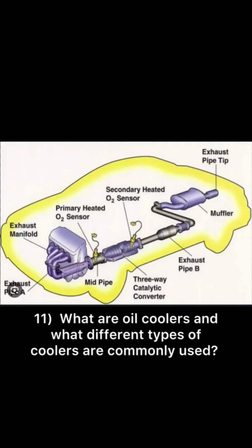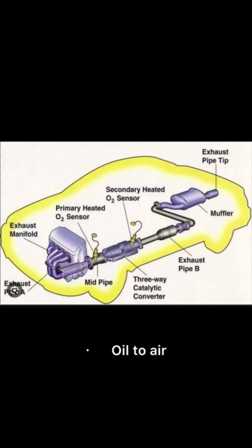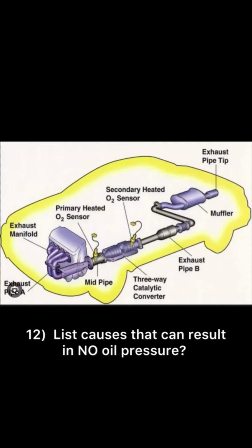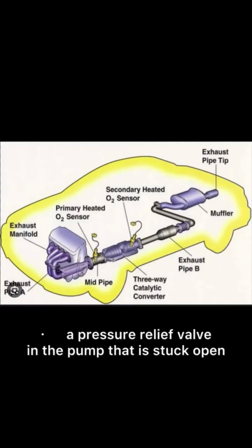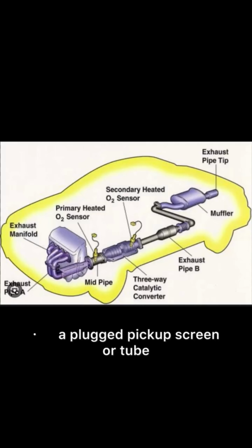11. What are oil coolers and what different types of coolers are commonly used? Oil coolers are heat exchangers that transfer heat out of the engine oil, cool the oil. Oil to air, oil to coolant. 12. List causes that can result in no oil pressure: low oil level, a pressure relief valve in the pump that is stuck open, a broken or twisted off oil pump drive, a plugged pickup screen or tube.